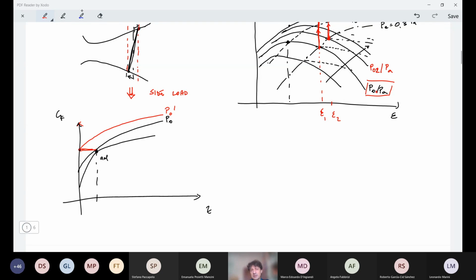This is the always adapted condition, but you will follow a new line, which is this one, because you are adapting at sea level, and it will be something less. But you see that this something less is always more than what you have in the former case. So if you are able to work at a higher pressure, it's better not to decrease it if you are looking for the best performance.